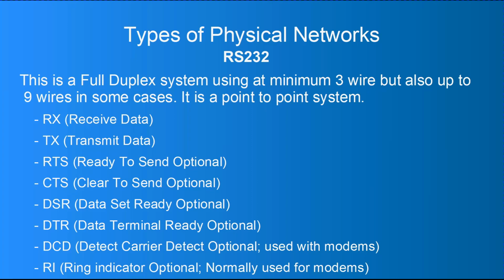Now, there's quite a number of wires used for data, not all of them with the DB9, but in the DB25, they actually had two sets of transmit and receive signals and a few other control wires as well. But normally you have a single wire for receive, another one for transmit, and these are supposed to work around the 15 volt mark. So you can see where charging the wire up to a higher voltage also creates issues.